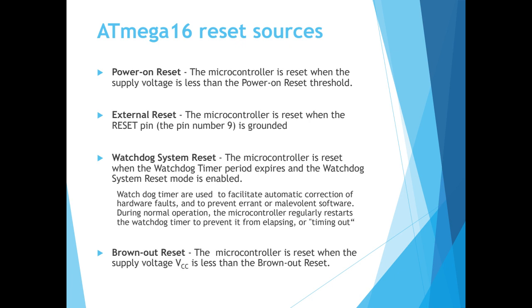There are different reset sources for Atmega 16, and with respect to our application, we can use them. One of them is power on reset. The microcontroller is reset when the supply voltage is less than the power on reset threshold. Another reset source is external reset.